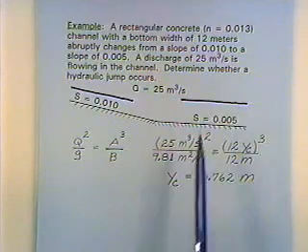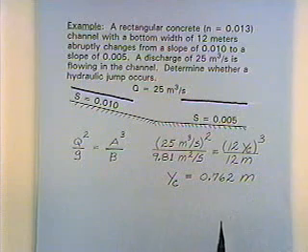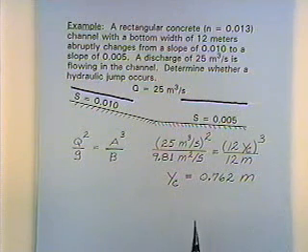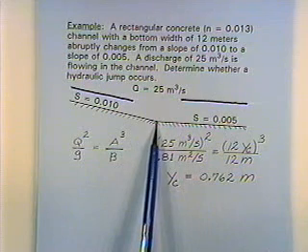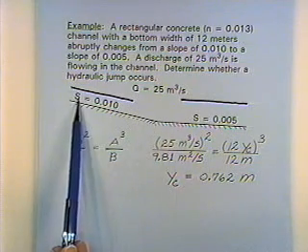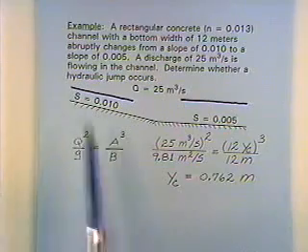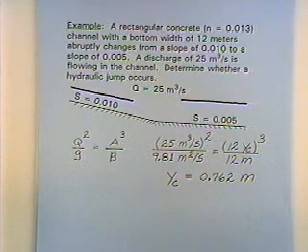And we're assuming uniform flow. We're assuming that there's no other irregularities or non-uniformities to cause any type of non-uniform flow other than this break in channel slope right here. And so if you get some distance away from here where this isn't impacting the flow depth anymore, Manning's equation would describe the flow here some distance upstream and would describe the flow here some distance downstream.